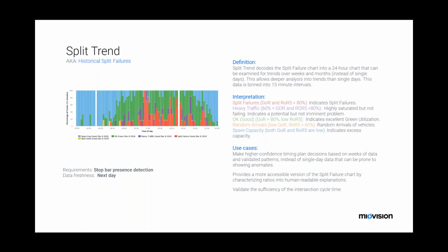And then you look at that across multiple intersections and multiple movements across the corridor, and you can start really assessing where time could be reallocated. And that's really where our intersection health alerts, if you're familiar with those, actually derive, at phase termination issues, suboptimal green splits. And what that may be causing is, like the most obvious one is probably your phase termination issue, which we talked about when we went into the intersection health tools.